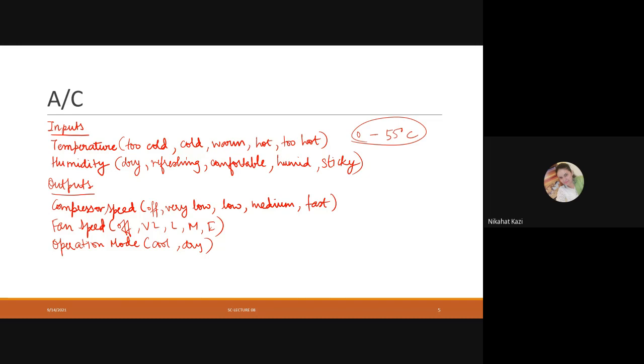I need to make fuzzy sets. So what will I do? I will make use of standard membership functions which I have studied. You recollect? What are the standard membership functions? Triangular, trapezoidal. Yes, exactly. These functions you will be using to cover these temperature ranges, humidity ranges throughout. And then after this, you will devise a set of rules. So you will form your rule base.